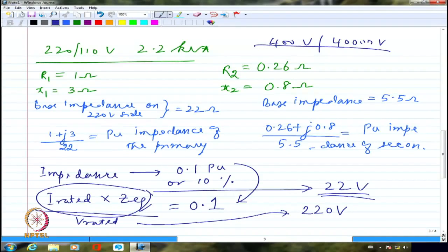Whereas, if I look at an induction motor, I can say normally the series impedances will add up to 25 to 30%. So, roughly we have the ranges for different machines. By just observing, we would be able to say whether the values are falling within the range. That's the first advantage. Second advantage is, you can just calculate the values from either side, no problem. You don't have to transfer one ohmic value from one side to another. Everything that will be given will be normally in percentage, which will be common for the entire apparatus, whether you look at it from the primary or secondary. So that's the major advantage of per unit, right?